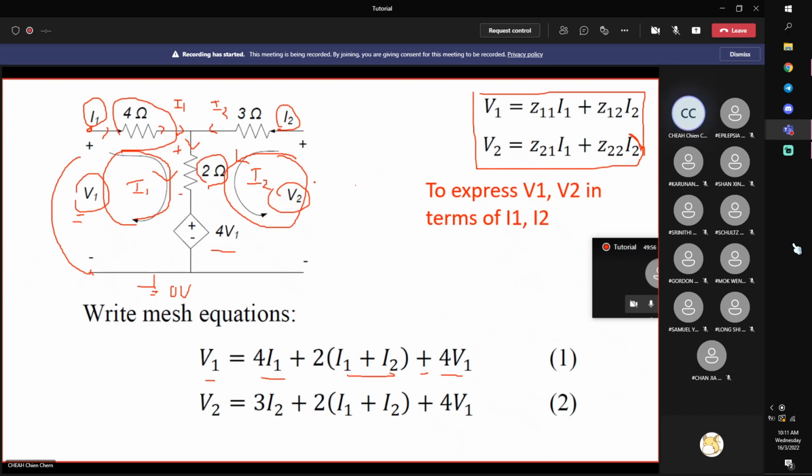So similarly over here, right hand side V2 voltage, and here I climb up by V2, and then I climb up by another voltage across the 2 ohm resistor. You can see this part is the same because this is a common branch between these two. And then I only need to add up the voltage across the 3 ohm resistor, high to low, right? High to low, so low, negative to positive, pass.